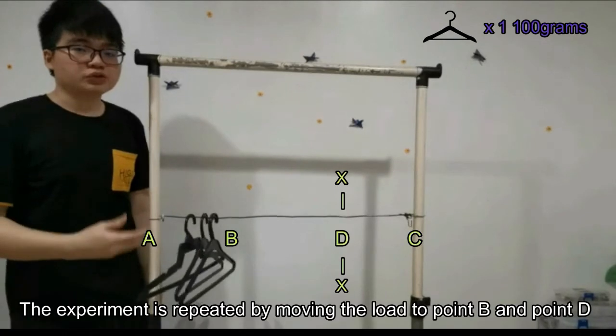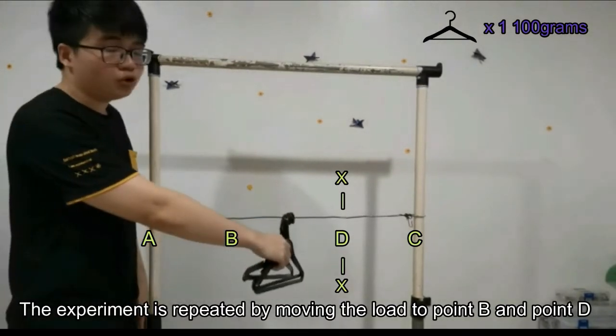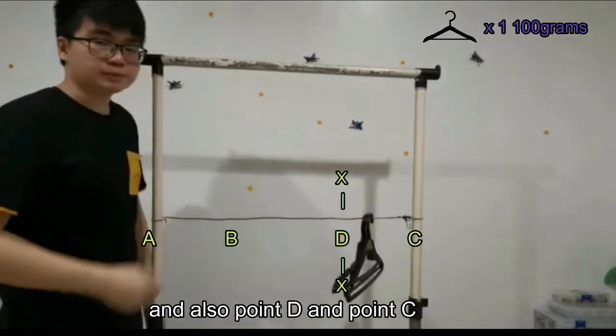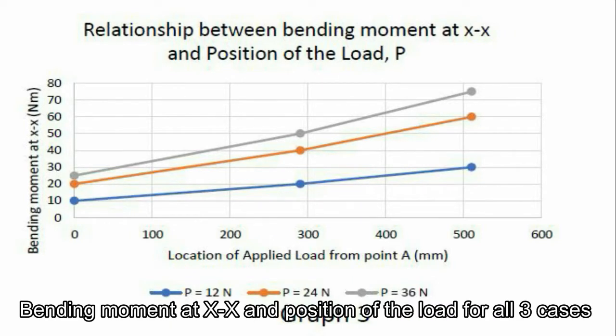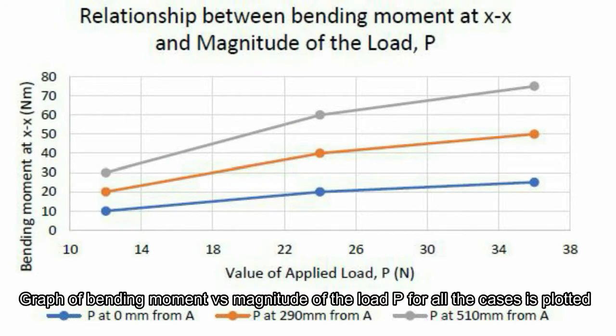The experiment is repeated by moving the load to between point B and point D, and also between point D and point C. Next, we need to plot a graph which is the relationship between bending moment at XX and position of the loads for all three cases. A graph of bending moment versus magnitude of the load P for all the cases is also plotted.